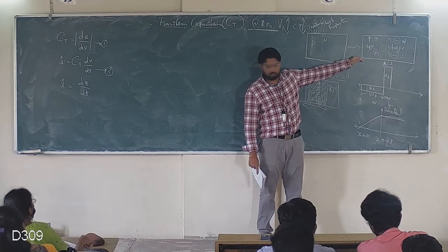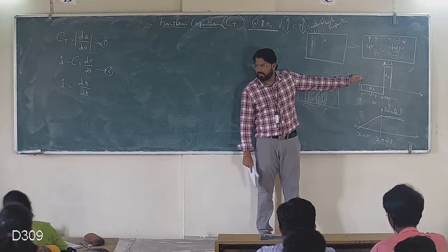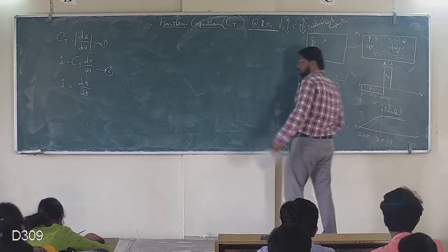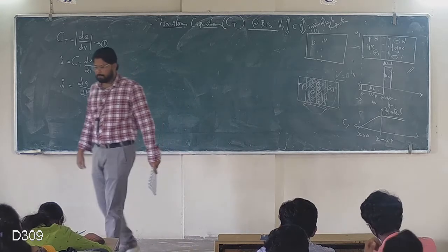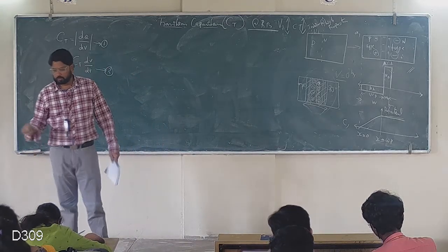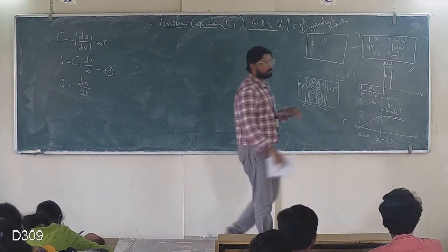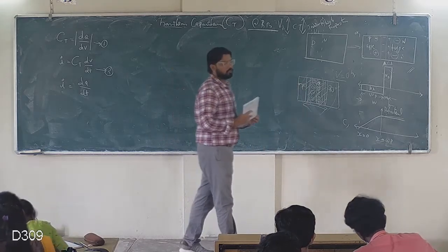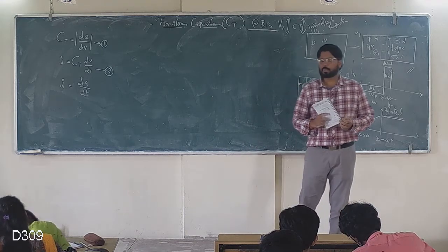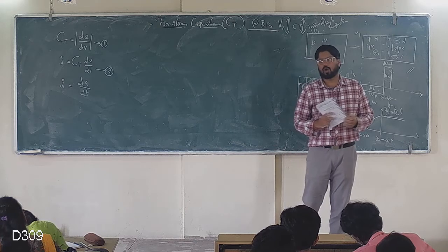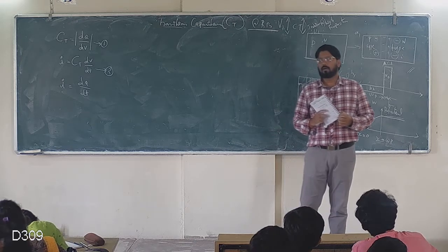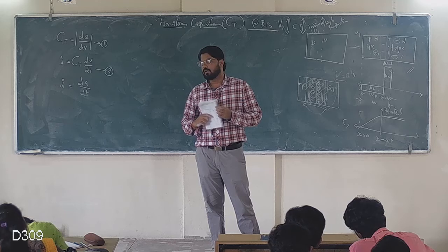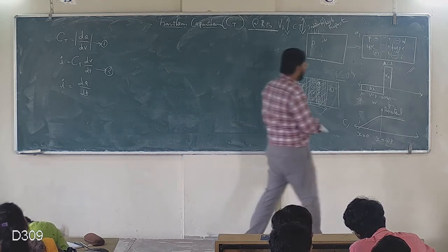A is the alloy junction, B is the charge density distribution across A, B and C. Small a shows charge transition, or injected minority carriers, across the junction.